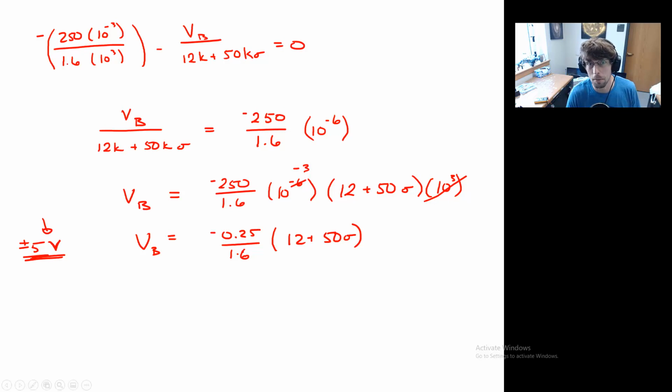That's because some of the energy needs to be used to actually operate the op amp. So if you have a 5-volt power supply, your saturation limits might be 4.5 volts, something like that. You have to check the specs on each op amp, right? It's all different depending on what you use in your circuit.